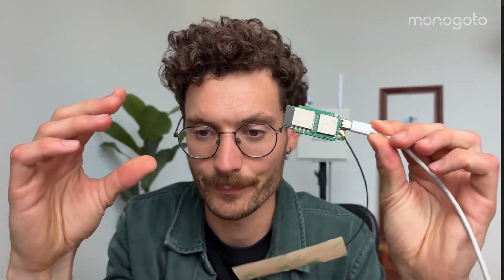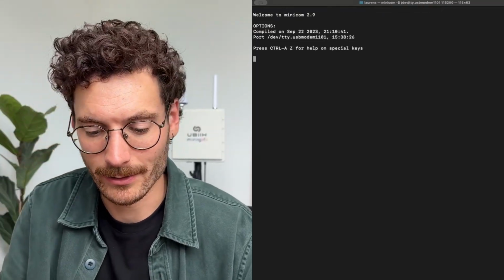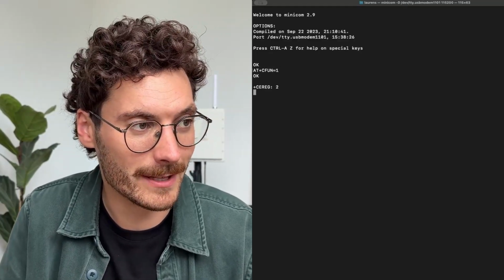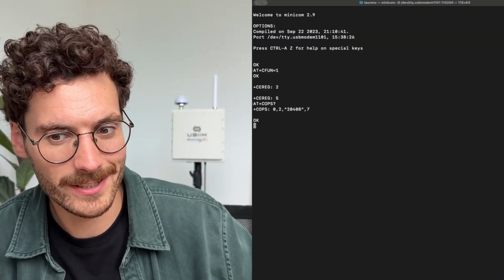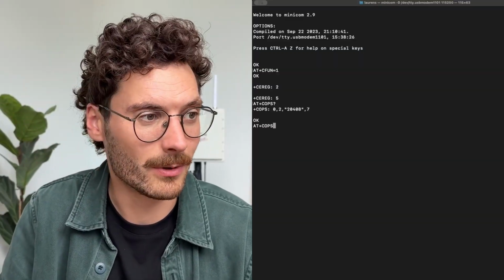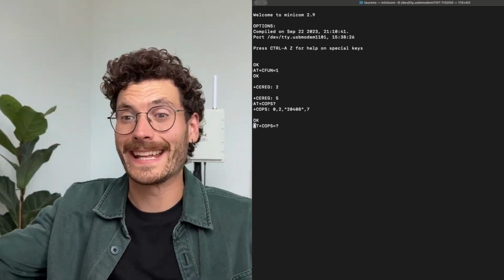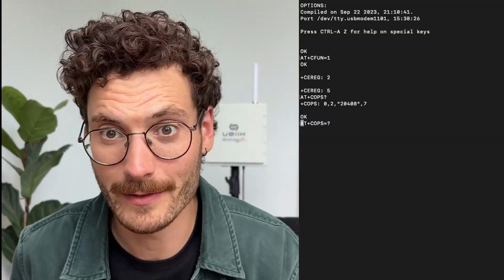Now let's try to connect an IoT device. So I'm using the Walter board, my dev kit, and I'm gonna connect directly to my computer. Then I'm opening up the serial monitor, allowing me to send AT commands directly to this device. So first, I need to turn the radio on. And I see that it's connected as of now, but it's not connected just yet to this private network. So what I'm going to do, I'm going to conduct a full network scan. So the device scans all networks around and hopefully it sees this private network as well. So let's give it a minute.